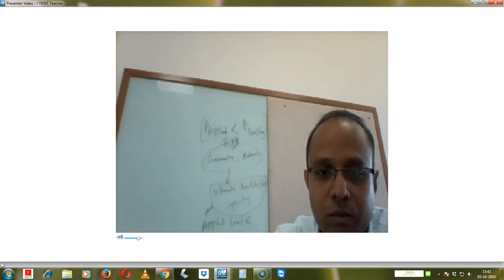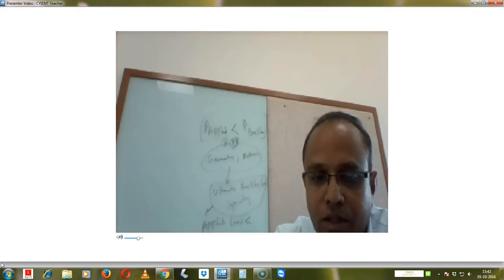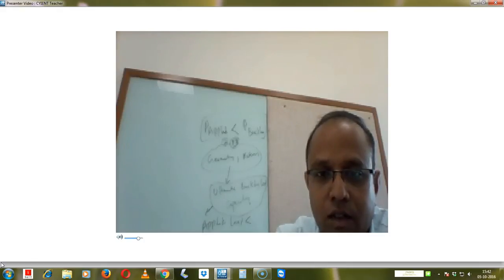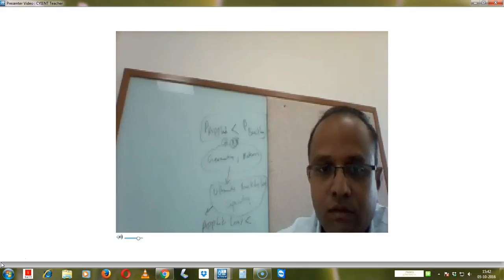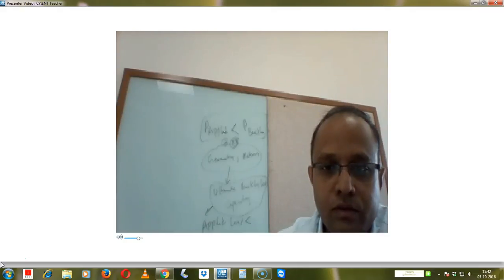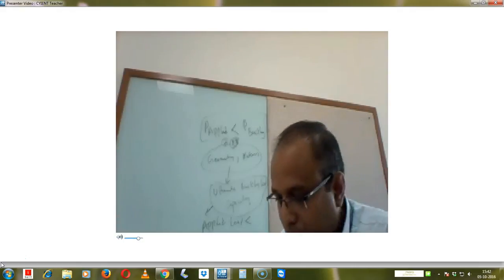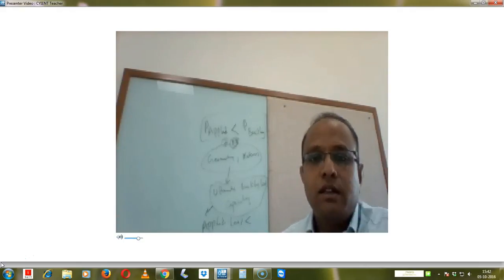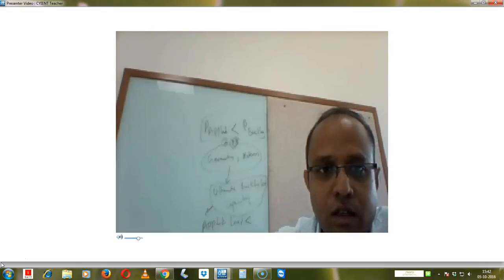Okay. So this is the worst condition. It's like a cantilever type of thing, with axial loading. One end fixed and the other end free will give the worst buckling load. Similarly, there are other conditions as well. So in stress analysis, basically, all these things are evaluated based on Euler equations.